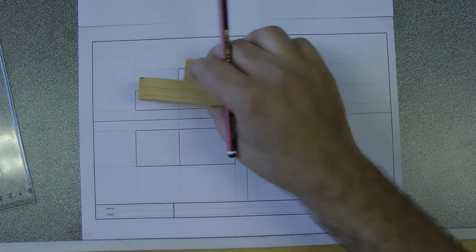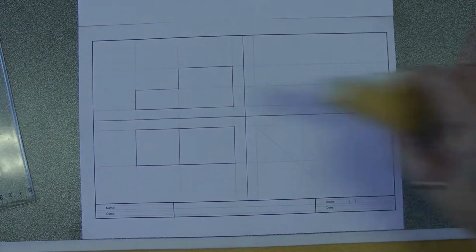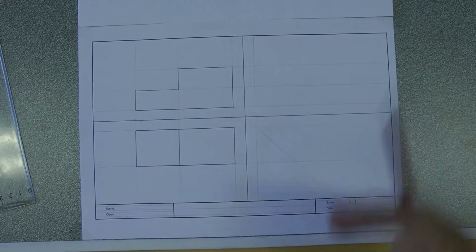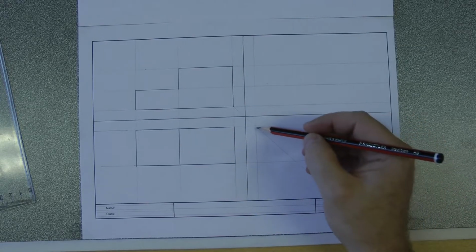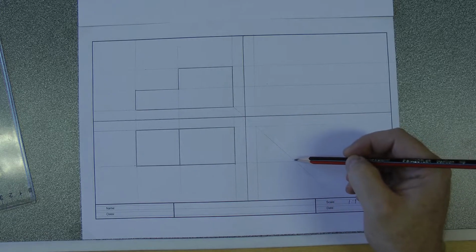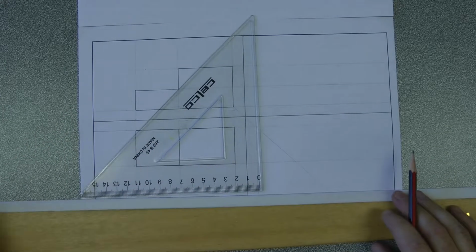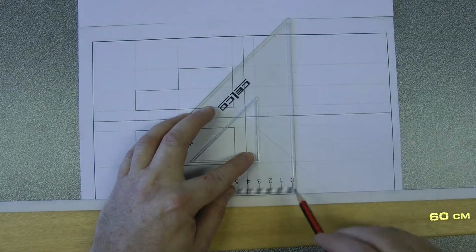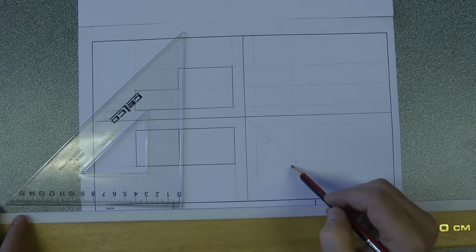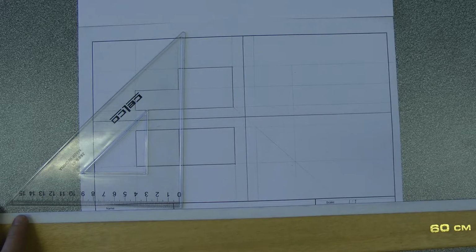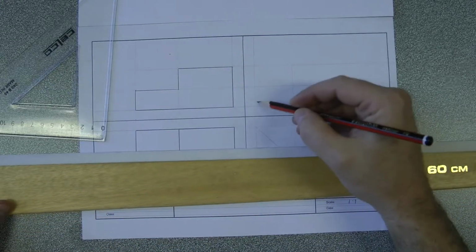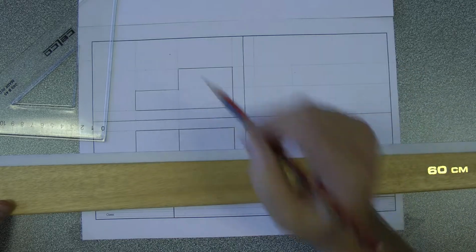The left view is on the right side because we have rolled this over this way, as the top view is below because we have rolled it down. Now we need the thickness of the wood of 35, and I can bring a ruler and measure 35, but we know that with a square, this line from corner to corner is 45 degrees. So we can use that by putting this up here, because if this dimension here on a square is 35, then this dimension here is 35, and it is a square because a 45 degree line connects corner to corner. And that gives me my basic outline of my left view. I've got the basic rectangle here, here, here, and here, and I've got the line here which represents that surface.